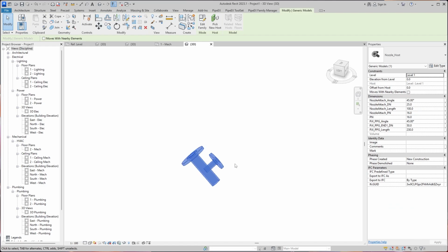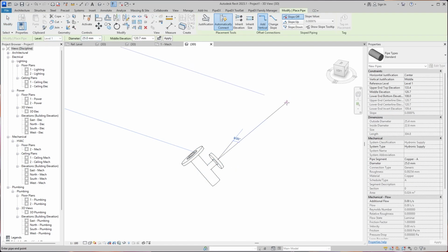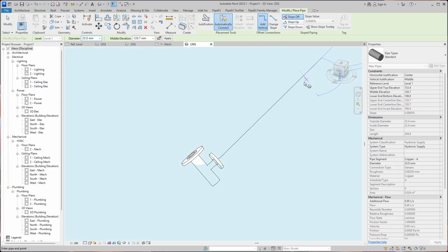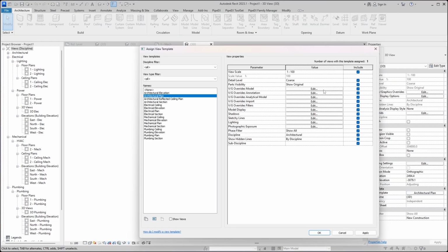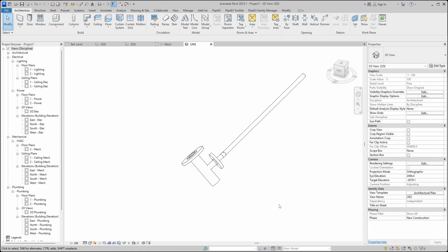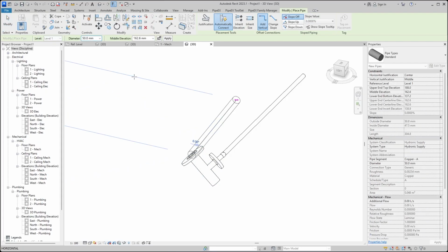in the 3D model, when we click on this nozzle with Tab, you can connect a pipe over here. So the only thing you need to do is click on Tab, and then you can connect the pipe.